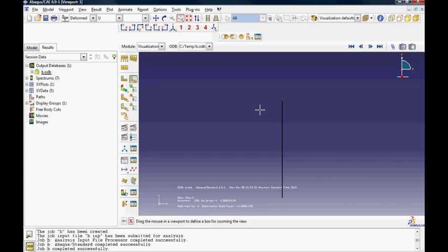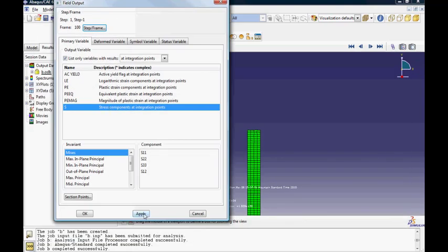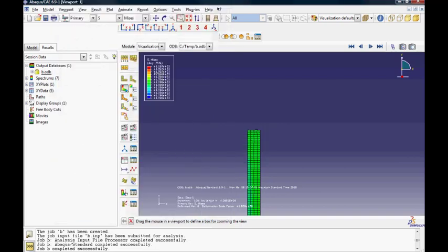And if we look at the stresses, I'm going to look at the von Mises stresses. Contour, it's 1.197 times 10 power 3, which is the maximum, the ultimate stress of the material. So basically this column or this plate has been compressed up to the ultimate stress without reaching any buckling. And of course, physically, this is not possible. So let's see how this will change when we change the initial geometry.